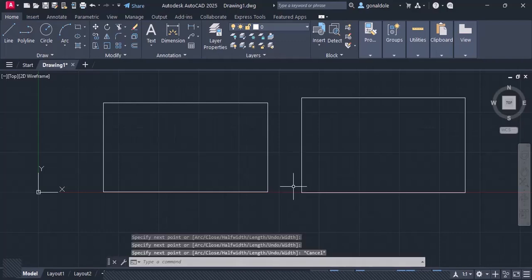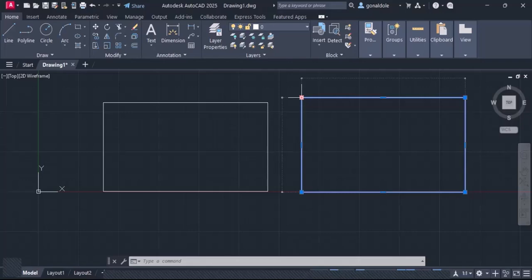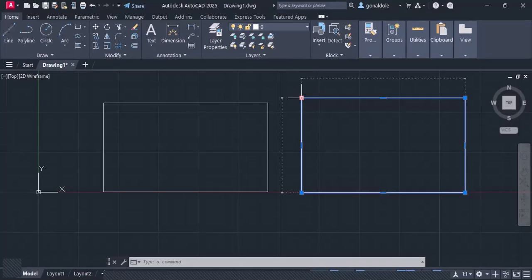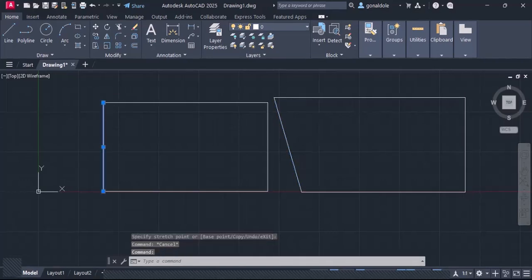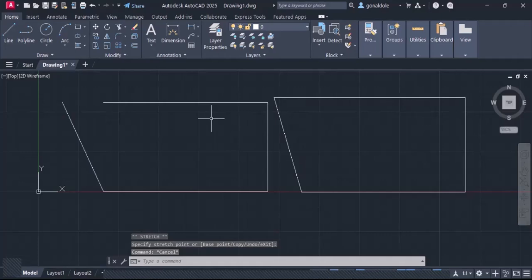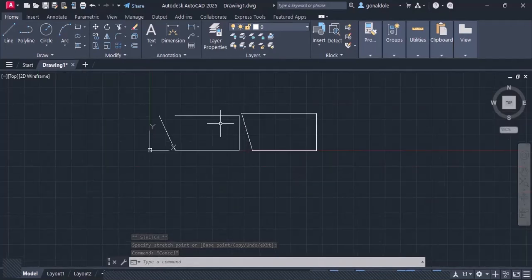Now, the difference between line and polyline. Once you click on the rectangle you drew with a line, you can click on each side separately. But polyline packs all of them as a single object. Once you select it, you're selecting the whole rectangle, which affects how you can adjust the attributes of the rectangle. With the one drawn with line, it's separate. You see, when adjusting, the other lines don't move with it. But there are many more features of using the line and the polyline too.